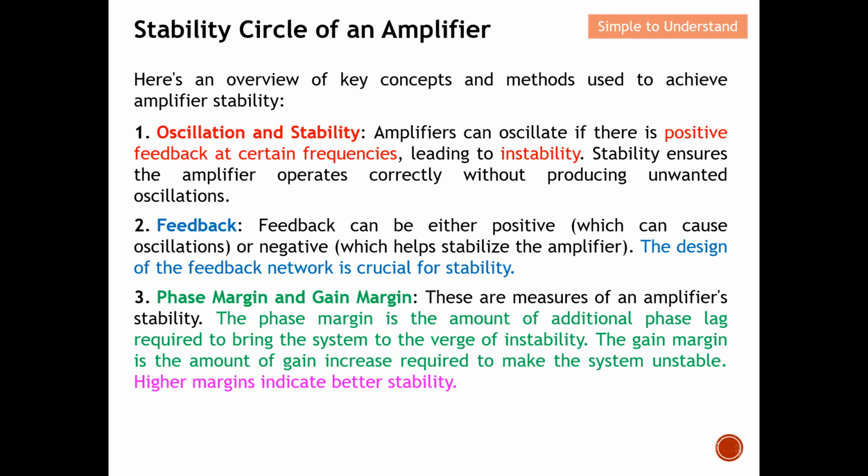How can you expect the amplifier to continue amplifying the signal if we have positive feedback? For example, I design the amplifier gain to be 1, later on it will be 1.1 amplified, 1.2 amplified, 1.3 amplified, and hence there will be a point where the amplifier will be saturated. Can you imagine this? The amplifier cannot improve the gain continuously. Once it becomes saturated, that's what we mean by the amplifier being unstable.